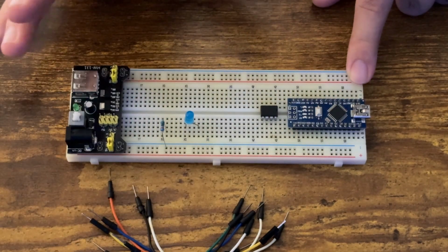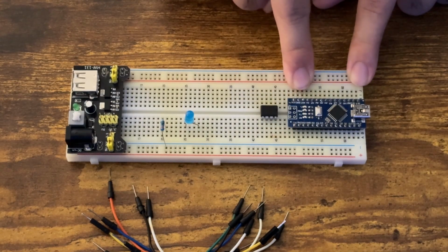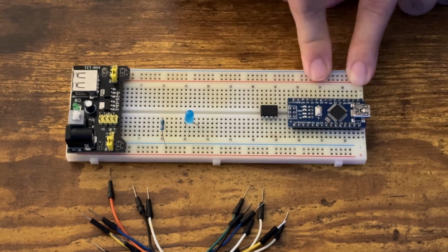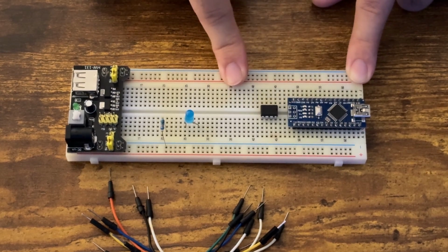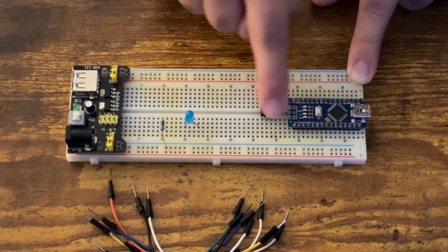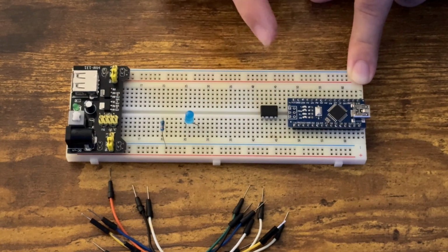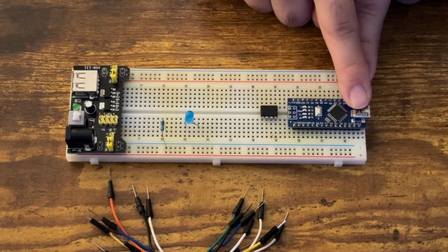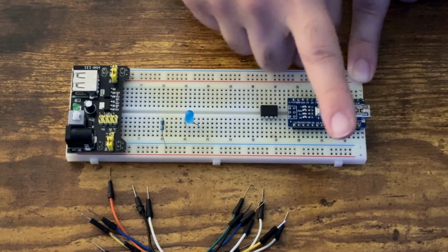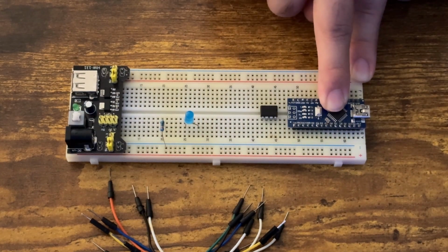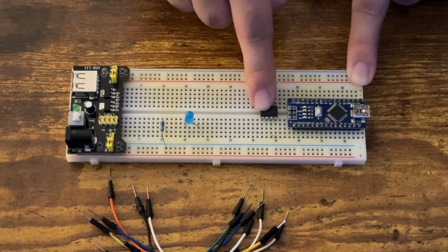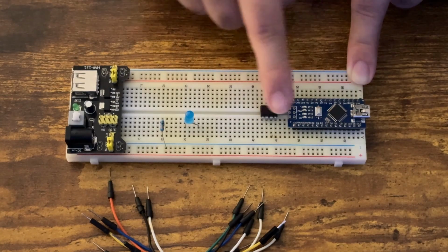So the way of transferring the code from Arduino to ATtiny85 will be SPI, Serial Peripheral Interface. This is just a communication protocol that we will use to transfer data from Arduino to ATtiny85. It is similar to USB, because USB is another, if I'm not mistaken, communication protocol, and we will transfer code from laptop to Arduino using USB, but from Arduino to ATtiny85 we will use something else, because ATtiny85 doesn't have USB, doesn't understand USB.